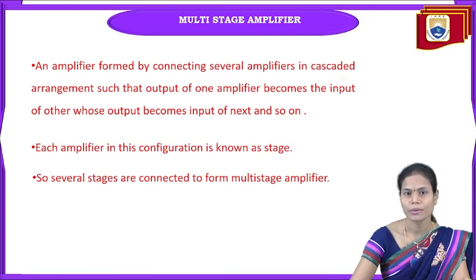So what is meant by multi-stage amplifier? If we interconnect two or more single stage amplifiers in order to make the multi-stage amplifier, what is the meaning of connecting the two or more stages? That indicates the cascading of stages. Cascading here means the output of one stage we are connecting to the input of the next stage.